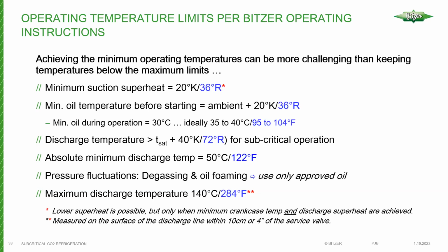But the point is, we want to avoid this altogether, because every time we do this, we're running the compressor in what we'll call an emergency situation, emergency running characteristics. The Bitzer compressors have this built into them, but you can't do this indefinitely. You will reduce the life of the compressor. Superheats are absolutely imperative with compressors in general.